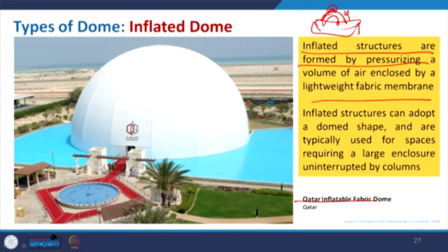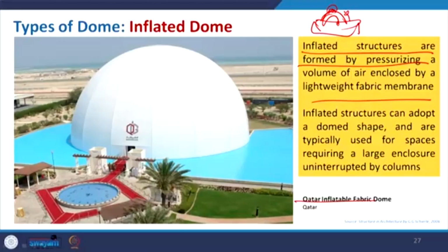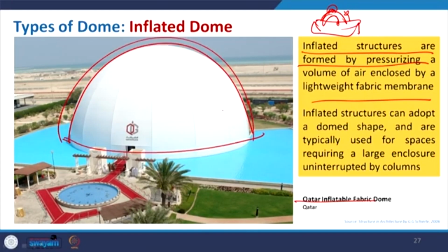This is not only for a structure; this kind of technique is now being used as shuttering to create domes. For a concave structure or a huge dome, unless you go for corbelling, it is very difficult to make the shuttering at a certain height and also to maintain perfect symmetry. So, we can take a balloon kind of form, put the pressure, cast the dome as we want, and then release the pressure so that it is removed very smoothly.